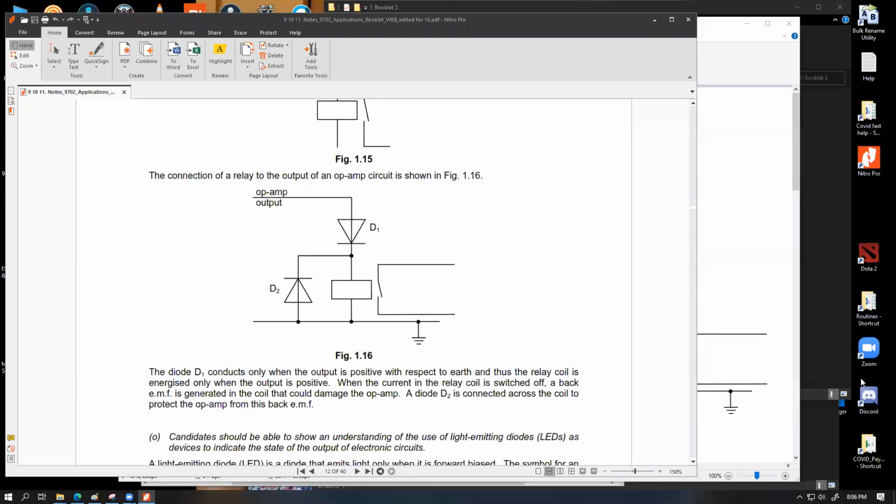Sir, another thing here is that basically the resistance of the solenoid is not high compared to the circuit? Which circuit? I mean the rest of the circuit. Well, in this case, this part of the circuit is supposed to work for the positive output. Now, whenever the op-amp is providing the positive output, for an ideal case, the diode doesn't have any resistance because it is in forward bias. So all the resistance is coming from the solenoid. For an ideal circuit, when the output is positive, the resistance is only from the solenoid. If the output is negative voltage, then the diode will take all the voltage, or will provide infinite resistance.